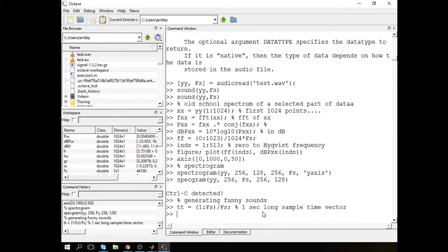Then I want, for example, a kind of undulating sound, like an ambulance does. So my center frequency would be about 1000 hertz, and that would change about twice a second, not faster than that.